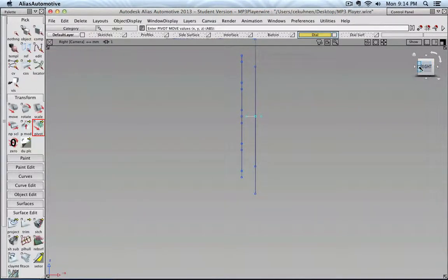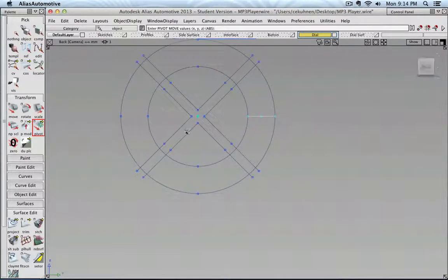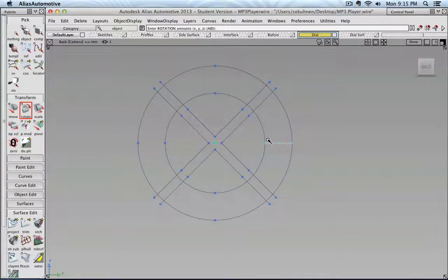So you can see that it's perfectly centered, because now when I go into rotate, and I know this is 45 along the x or minus 45 along the x-axis, you see z and y. So the rotation axis I would like to use in half is x. So I can type in minus 45, comma 0, comma 0, press enter. And then that arc is positioned down here.